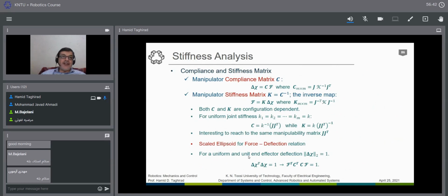So this means that we have the same ellipsoid as before, and I hope that you have examined it; it was two sessions before that we defined eigenvalues, eigenvectors, singular values there, and the ellipsoid, the shape that this can become. And if the system becomes singular, instead of having an ellipsoid, we have a cylinder, a very tall ellipsoid. And this causes some issues in terms of singularity.